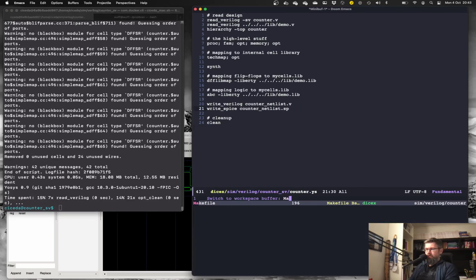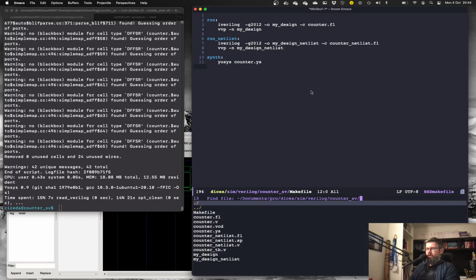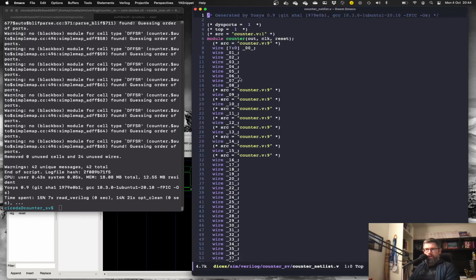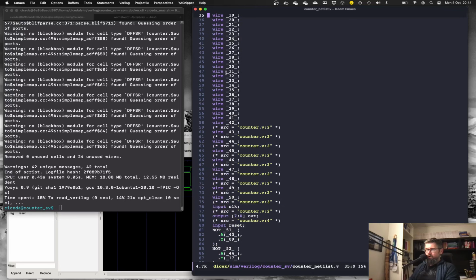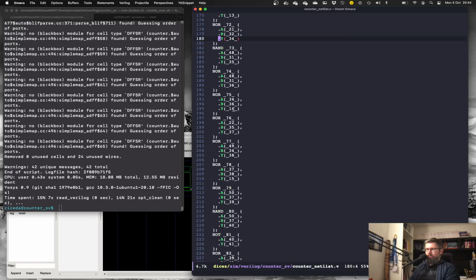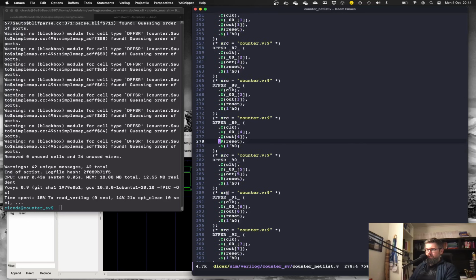If we look in our make file, then that's running just this yosys with this script, Tcl script. If we then open up the counter.netlist.v, we will recognize that we have now a bunch of wires. We have the NOT gates, and we have NORs, NANDs, and D flip-flops.